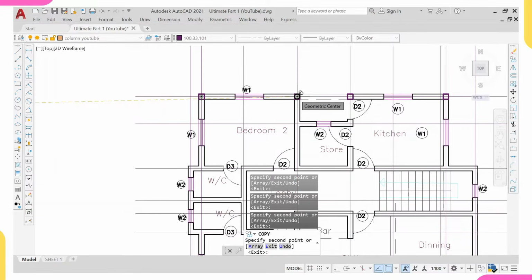And what it implies is that the more the span, the more the moment, and the more the reinforcement that you will be having. For example, if you go beyond 6 meters, you might be having, let me say, 5Y16 or even 3Y20 or even 2Y25. Since we don't really want all this larger reinforcement or too many reinforcement bars, that's why we advise that you should limit your column spacing to below 6 meters.